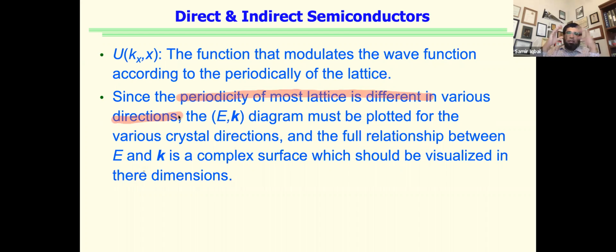If you go back to that lattice cube concept that we introduced in the first chapter, a bunch of cubes stacked next to each other, if you're going in the x direction, you encounter atoms at a certain distance. But if you're going in the xy direction, at a diagonal, the next atom may come at a later distance, further away than in the other direction.